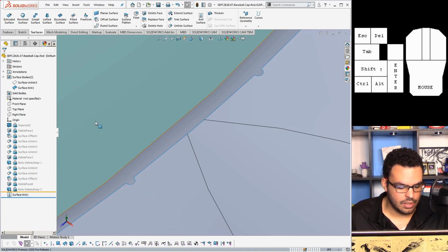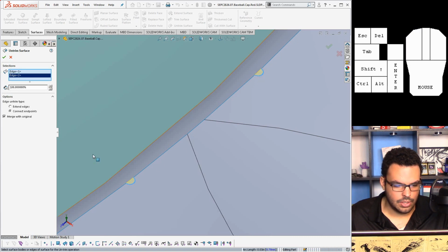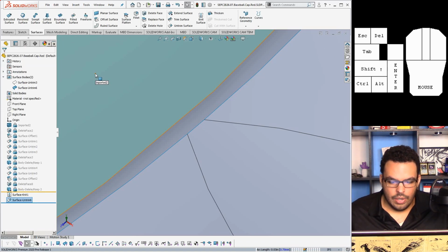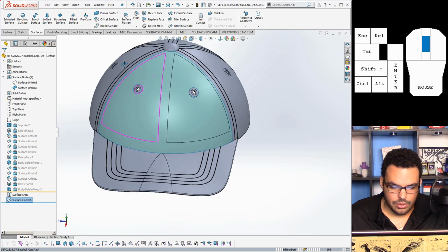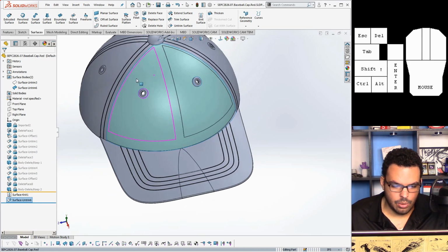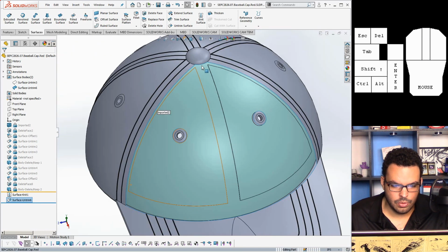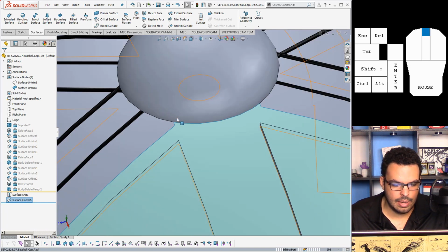And let me move my freeze bar a little bit forward. Untrim, do this, click on that. Make sure you have connect endpoints. That's how it knows to patch that over, and just let it work its magic. All right, that seems to have resolved itself very nicely, actually. And now I think this is clean enough for us to use a patch. Again, this is a questionable area, but we'll see if it gives us any problems.